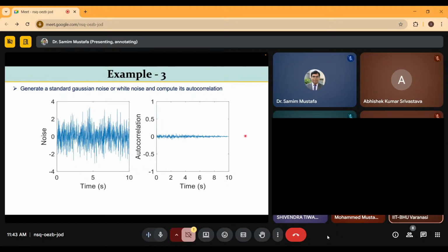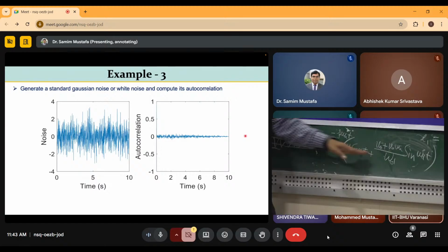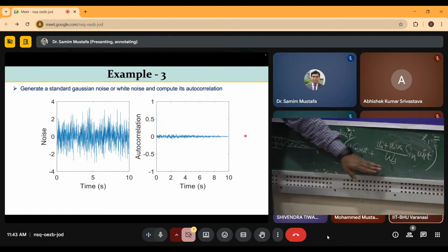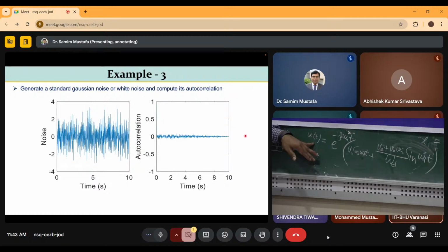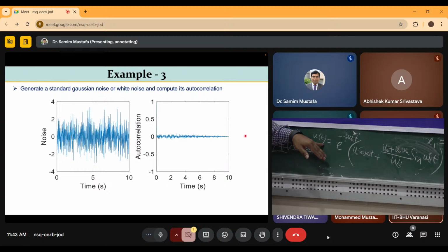Omega d t, this type of equation is there. If you solve the free vibration response with damping, why not write the equation in MATLAB or Python, just varying the time. You specify the xi, some damping, probably 5% damping. You can assume every structure has 2 to 10% damping. If I assume 5%, xi will be 0.05.